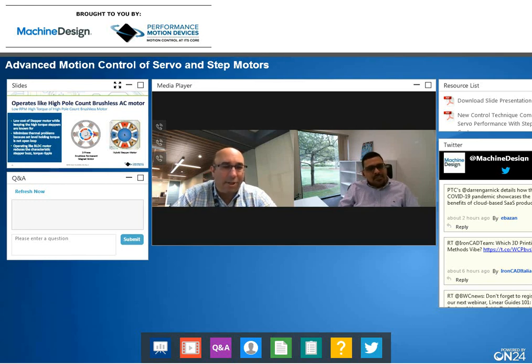Yes, and there's a lot of industries where you end up either putting finer ball screws into the application to get the RPM levels up in the permanent magnet brushless motors so that you can do the work you're requiring, or they're really using the brushless motor in an area where it works decently, but not as well as it could, because those applications never have to go that fast from an RPM standpoint.